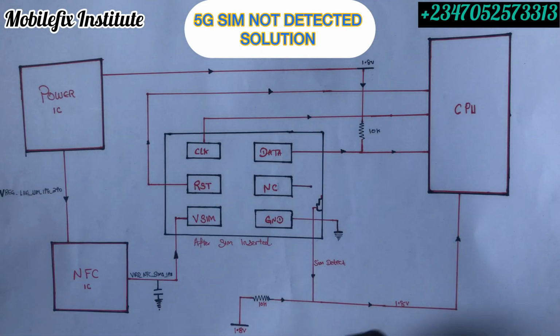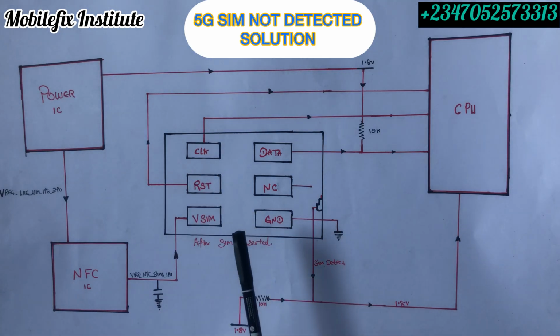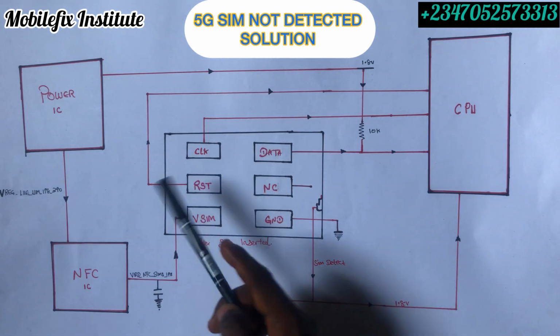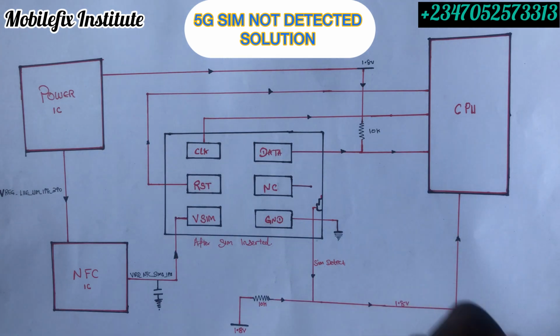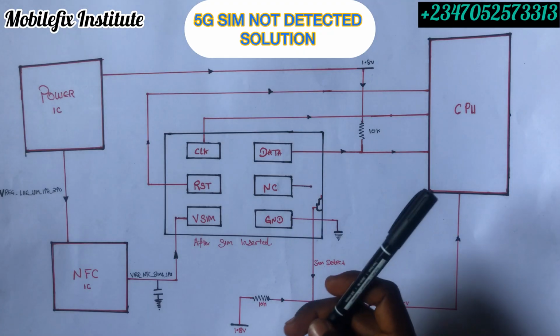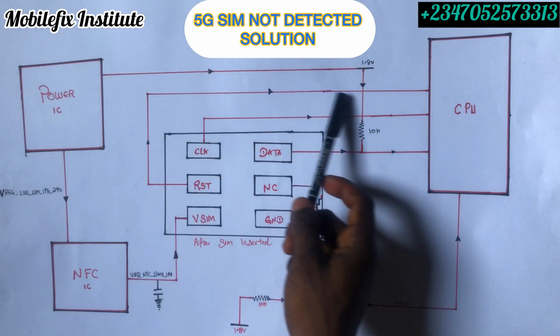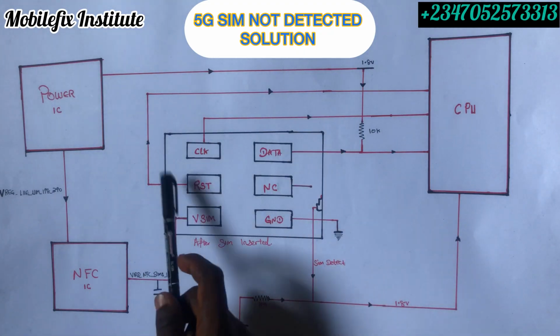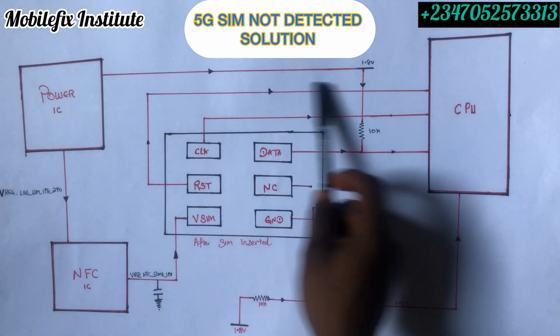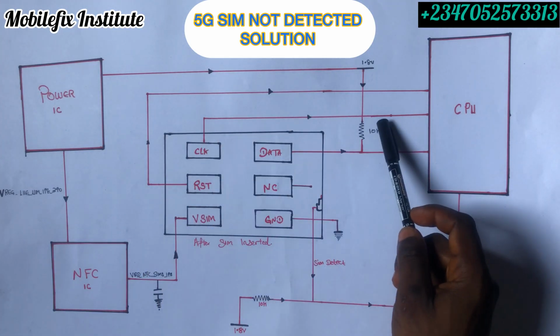After taking the readings, if you discover that any of these pins is having a short, giving you a beeping sound, you have to work on that particular pin, because there are capacitors connected in each of the pins. Each of the lines that is connected from this pin to our CPU has capacitors.